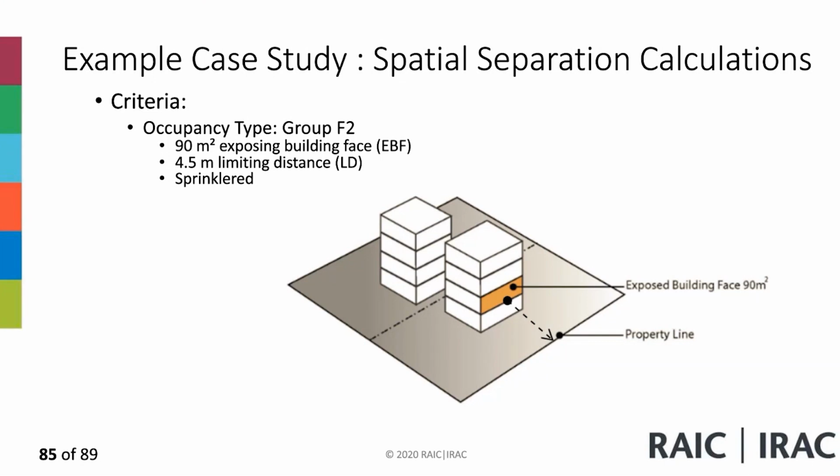Now, depending on which jurisdiction you work in, in the NBCC you can do interpolation of the numbers. Based on between 4 and 5, you take half the difference, so you can actually increase the area, and that's allowed best practice. But if you're looking at the table by itself, then you take the most conservative approach.